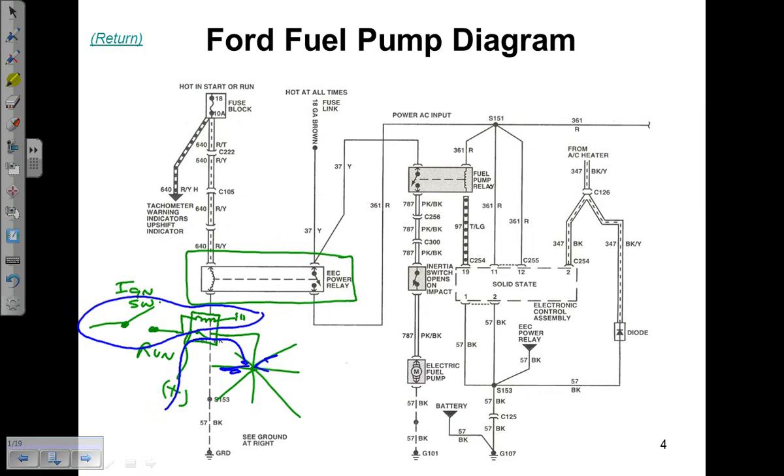So it's a unique design. What else is unique about it is you have the load side of this EEC power relay controlling power to the control side of the fuel pump relay. And so why am I talking about this within the fuel pump circuits? Is you can have a bad EEC power relay that's causing a no fuel pressure problem.